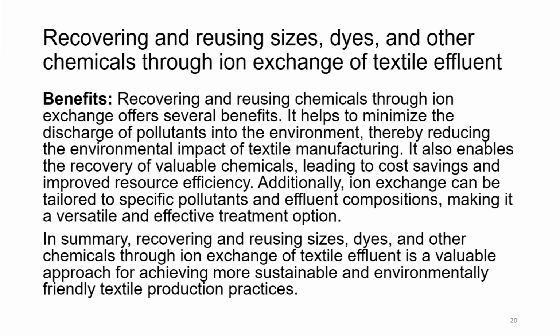It helps in minimizing the discharge of pollutants into the environment, thereby reducing the environmental impact of textile manufacturing. It also enables the recovery of valuable chemicals, leading to cost saving and improved resource efficiency. Additionally, ion exchange can be tailored to specific pollutants and effluent compositions, making it a versatile and effective treatment option.